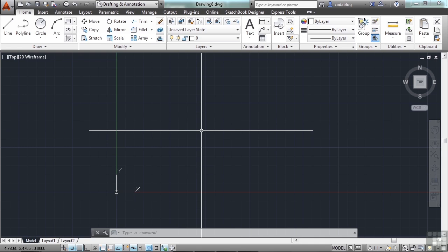If you need to draw objects at incremental units or factors thereof, then snapping is a great way to go. It helps you to draw in these increments every time without doubt and without tedious data entry. The snap technique is not very useful though when you are zoomed way out or you're too far away, because the farther you're zoomed out, then the more difficult it will be to see where you're snapping to. So it's a relative thing. You'll have to pay close attention to your coordinates in this case.